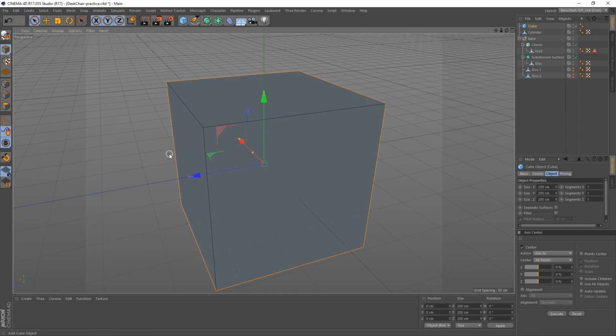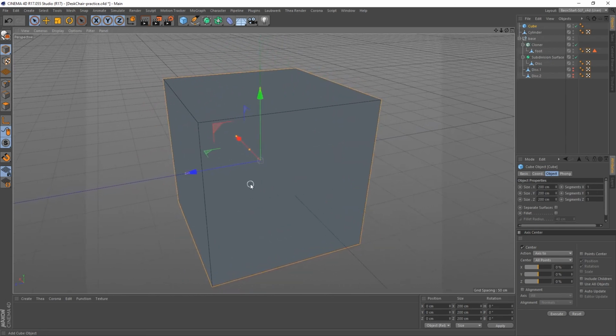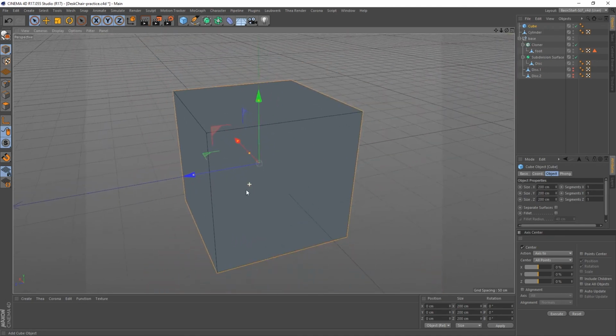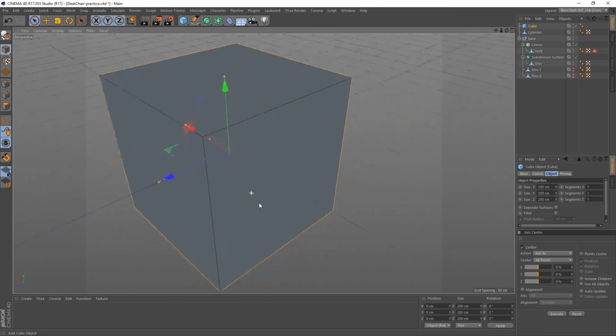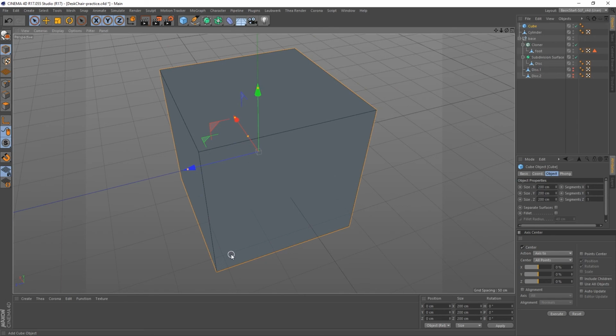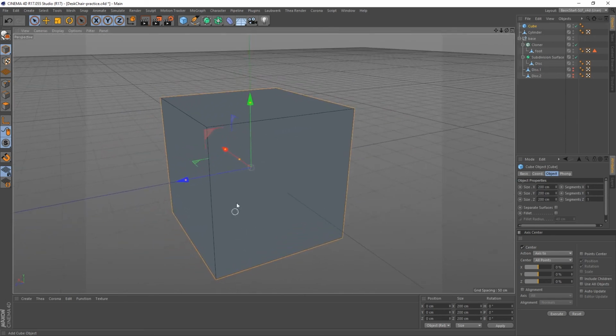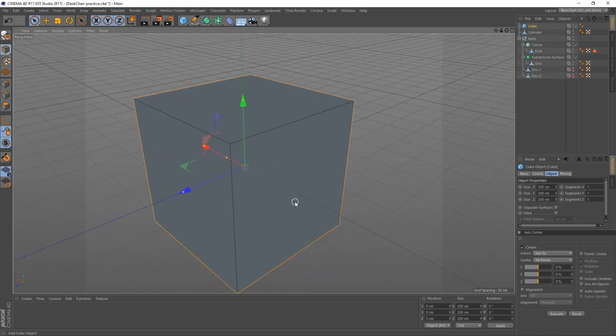And if you hit 1, the 1 on your numpad or the 1 on your keyboard right above the Q, if you have a QWERTY keyboard, and you left click, it's also pan. 2, left click is zoom in and out. 3, I'm holding down 3 and left clicking, and it's orbit. So there's another option for your zooming, but I suggest you get used to the Alt key and left click for orbit. That's going to be your most commonly used navigation.